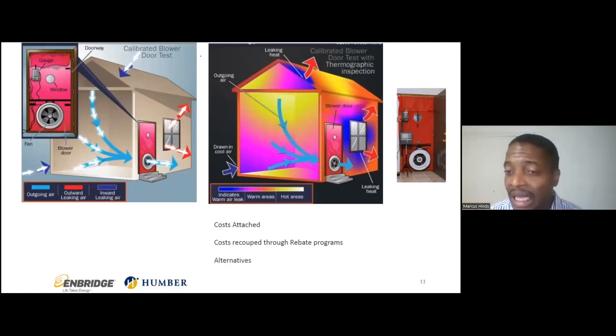The main thing that they're looking for is where that air replenishes itself from. Is it coming through your window frames? Is it coming through your door frames? Is it coming through your drains? Is it coming through your light switches, your electrical sockets? Where is that air coming from? How is it getting in? The main thing they're doing there is trying to figure out how exactly they can seal it up.